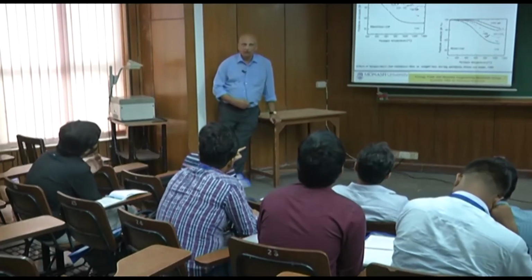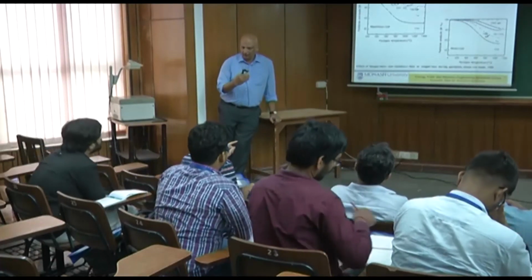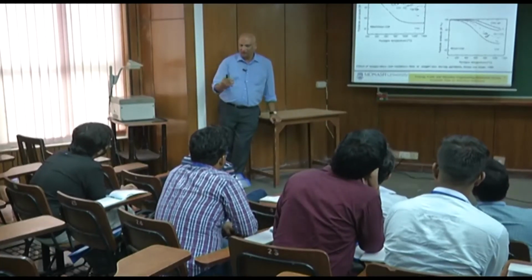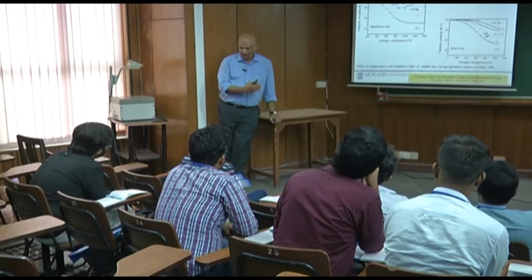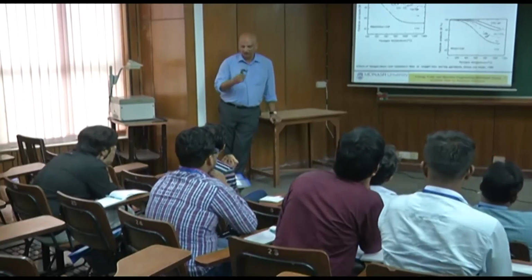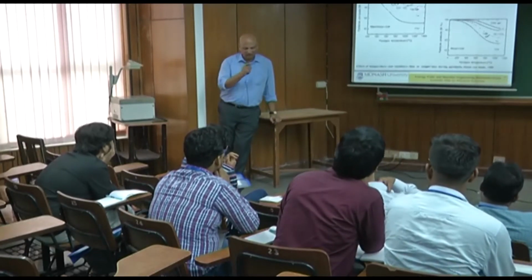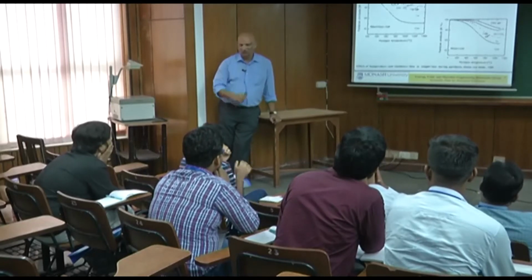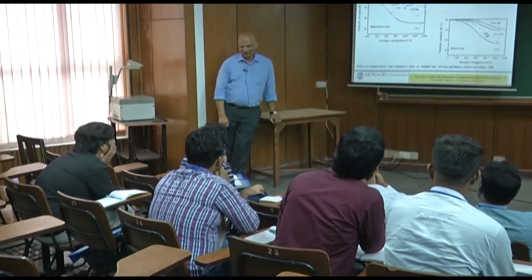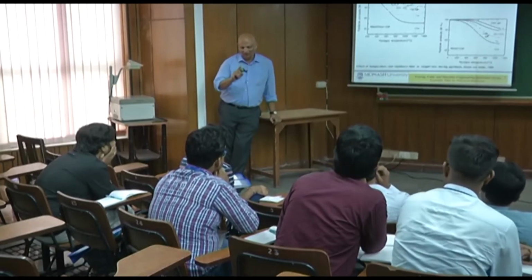At what rate the particle is going from 200 to 400 to 600 to eventually the gas temperature, that will be dependent on the nature of the particles. Nature of the particles means what's the size of it. The finer it is, quicker it will go. Irrespective of that, if it is in the PF size, 10 to 100 micron, from brown coal to bituminous coal, it's not going to matter all that much. So it's not temperature cycling at all. It's just seeing one rapid temperature rise.